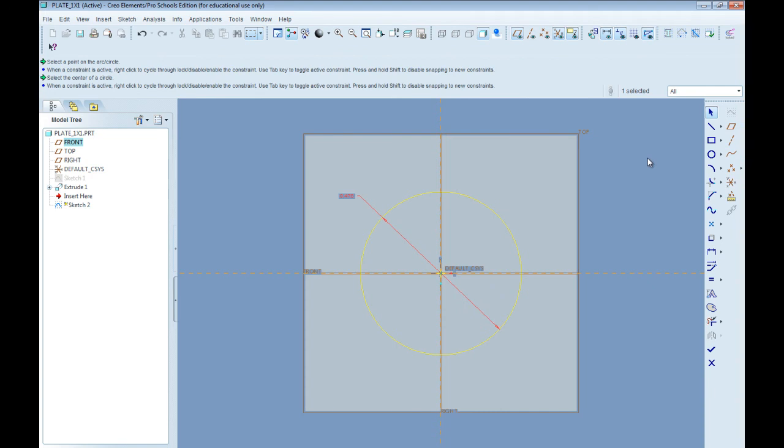From there on, before we exit out of this, we can check, just to show you, when you're extruding parts, if you have, let's say, a strange shape that you're working with, or you're having issues with extruding after you created your shape, you might want to check whether what you're extruding is actually closed or not.